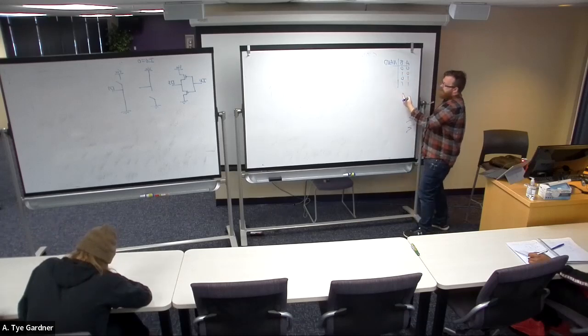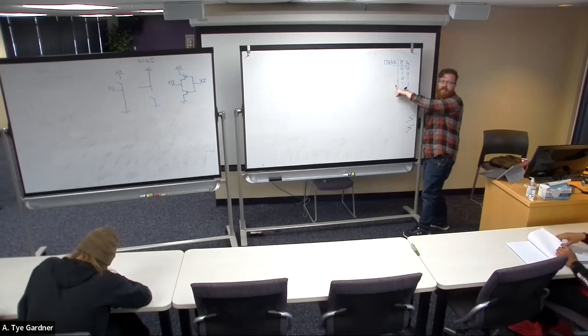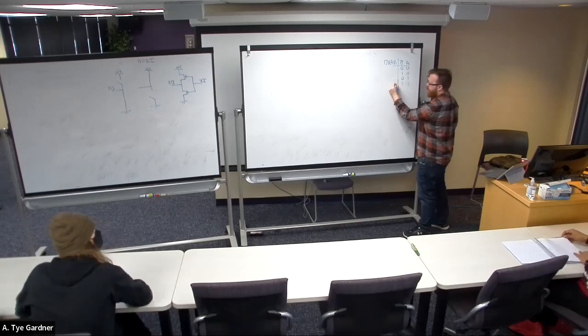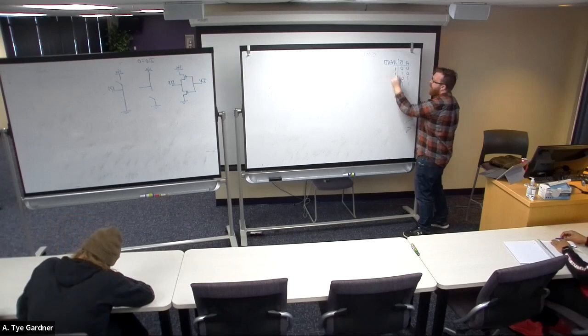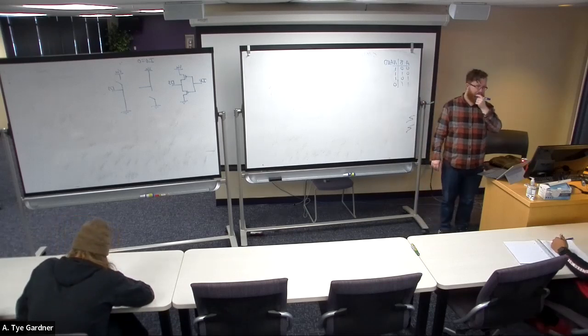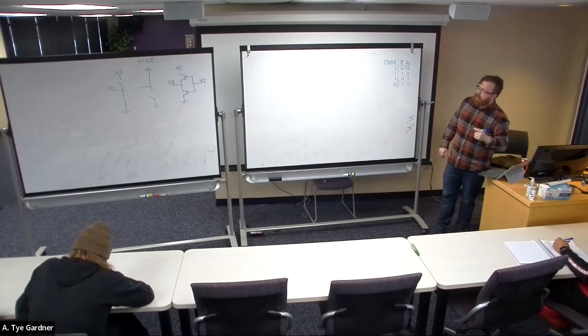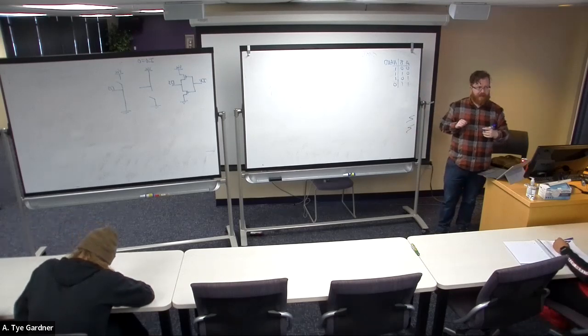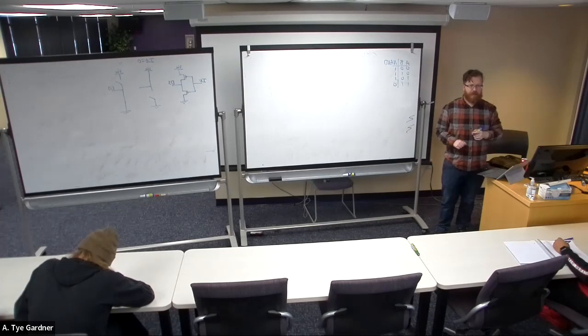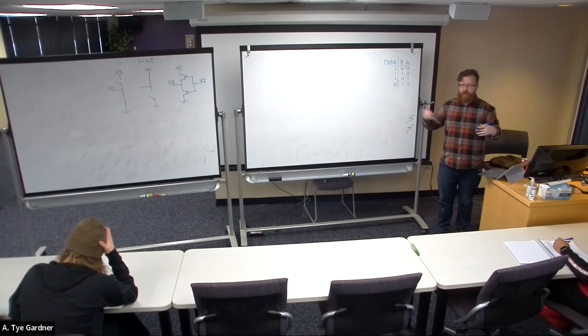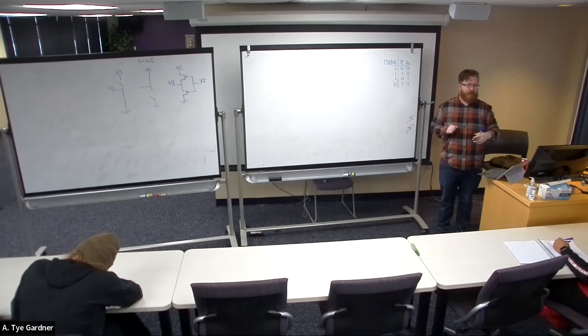The AND gate, right, would have a 1 here and zeros everywhere else, which means the NAND gate is not the AND, which means I get a 0 and three 1s. This is the truth table. And we know that the pull down network is responsible for the zeros. So we get to design this first by the pull down and then by the pull up.